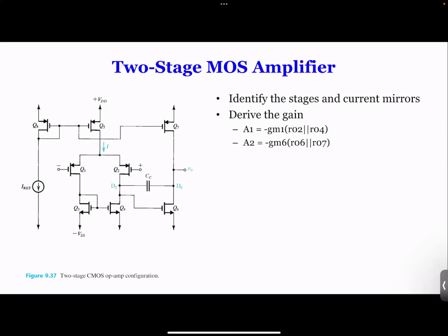But if you want to get rid of that DC, you have two methods. You can add a capacitor. The capacitor looks like a short circuit for high frequency. Therefore, you only see the AC. On an oscilloscope, in fact, you can measure DC only, AC only, or AC plus DC. So if you get rid of the DC offset, you will see AC only, right? So those are the two things that you have to look at.